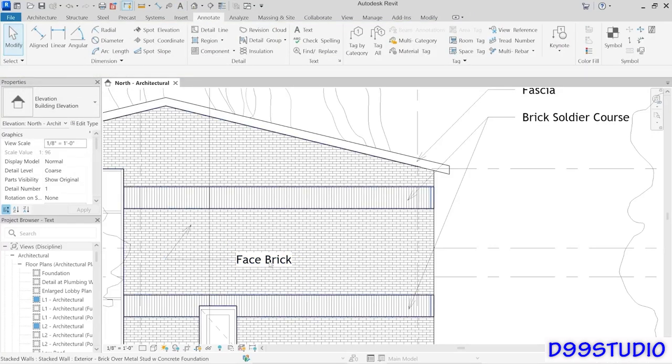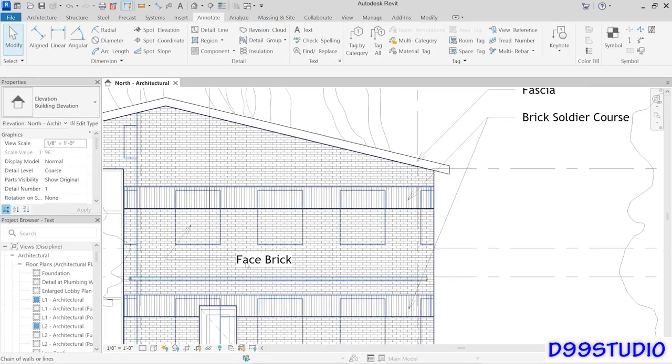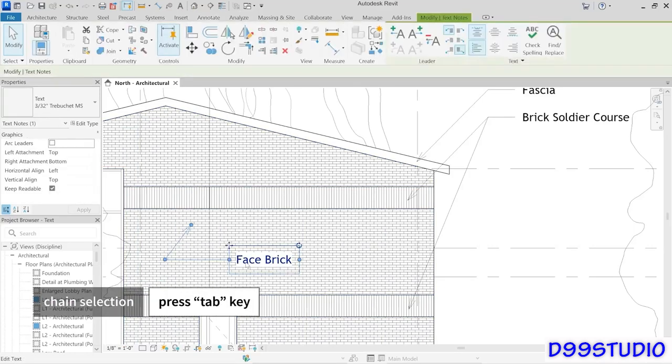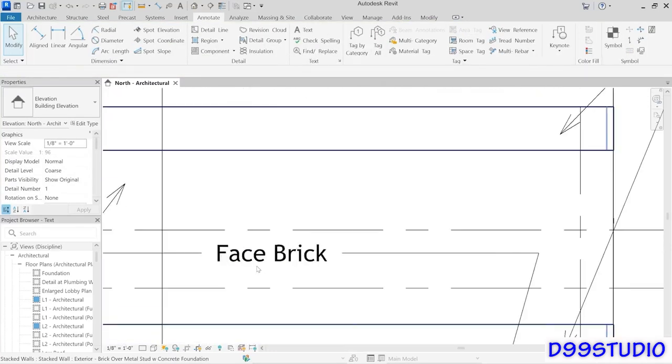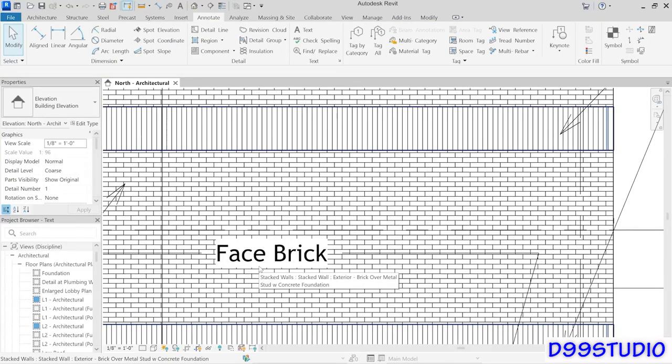I want to come back and select. Notice it's a little tricky. You might need to use your tab key, and it might take a few tries of tabbing to get there, but I'm going to select the note, add another leader line on the right, point to somewhere here, add my elbow, like so. And what I wanted you to notice here is that by default, text has a masking option. So there is an opaque background on this piece of text.